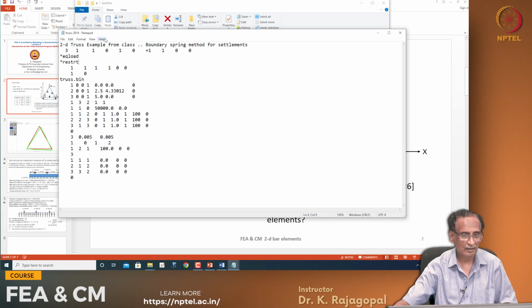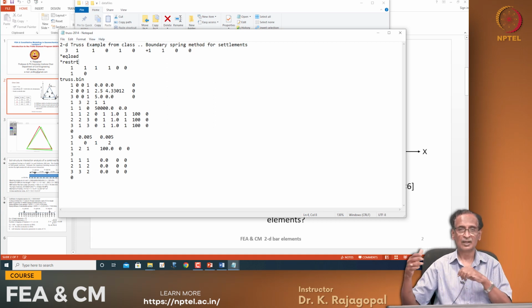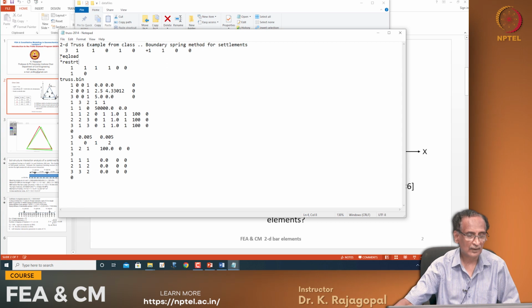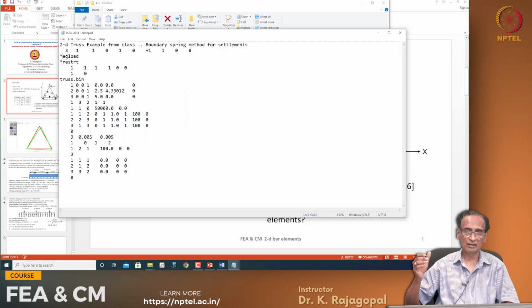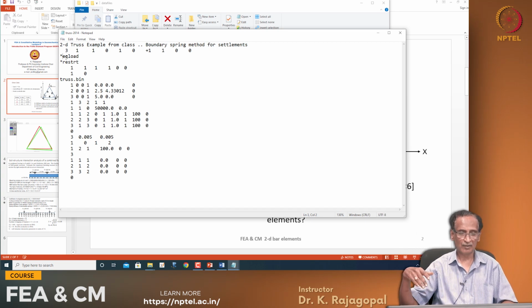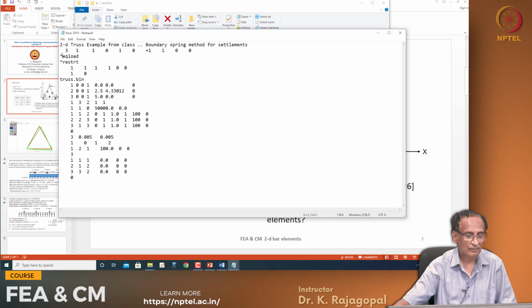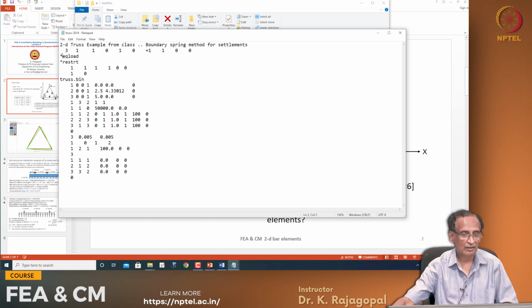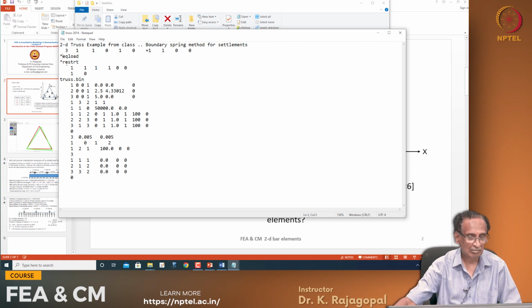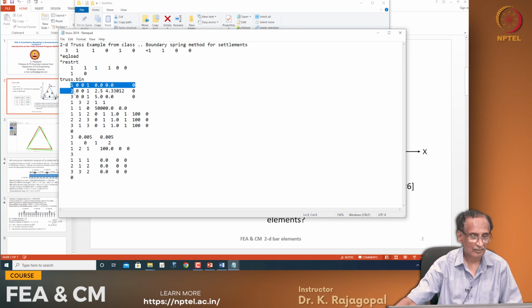And for restarting, the finite element program has to read some files. So it is going to read from these 2 files, and if you put a star in the name, it will be opened as a temporary file. So you will not be able to restart. If you restart, it will start from the beginning. Okay. And so if you want to restart any analysis, we need to give a name without a star. Okay. And your Young's modulus, these are the element coordinates, and then the